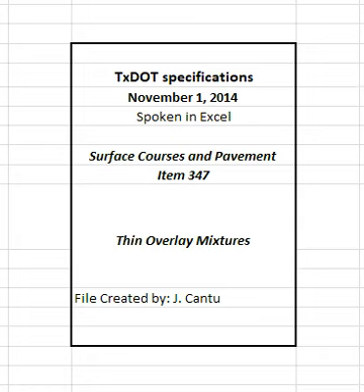Produce mixture with a department-approved WMA additive or process to facilitate compaction when the roadway surface temperature is below 60 degrees Fahrenheit or when the air temperature is 60 degrees Fahrenheit and falling. Produce the mixture with the WMA additive or process at a target discharge temperature higher than 300 degrees Fahrenheit.